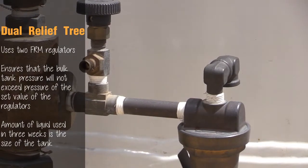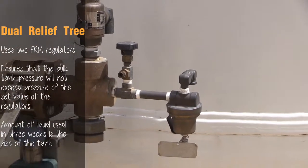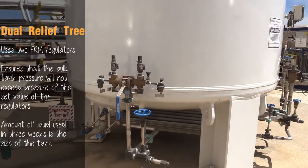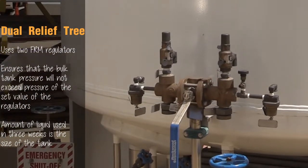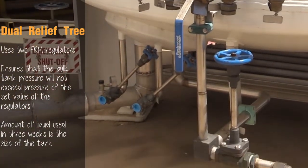One basic rule of thumb on sizing bulk tanks is to use the amount of product to be used in a 3-week period as the size for the tank. An example would be for a system that is going to use 1,000 gallons per week, a proper size tank would be a 3,000 gallon tank.